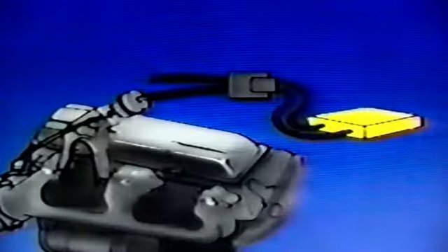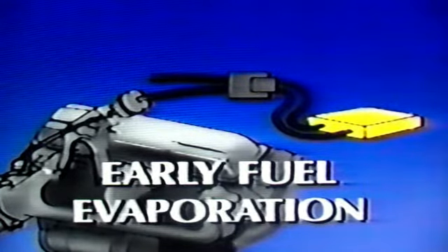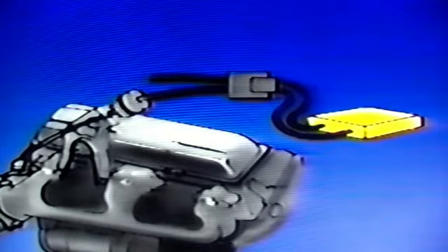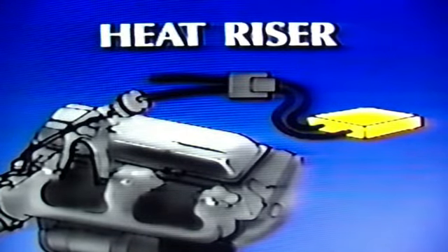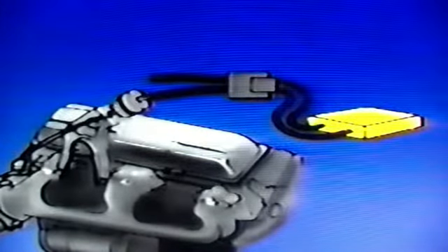the torque converter. The early fuel evaporation system, EFE, is also controlled by the ECM based on coolant temperature. There are 2 types of EFE systems: a vacuum-controlled heat riser and a heated grid. As you know, heat risers have been around for a long time, but we've made one modification. We've added a vacuum motor which forces it closed with engine vacuum when the engine temperature is low. After the engine warms up, the ECM controls a relay that releases vacuum and the valve opens.